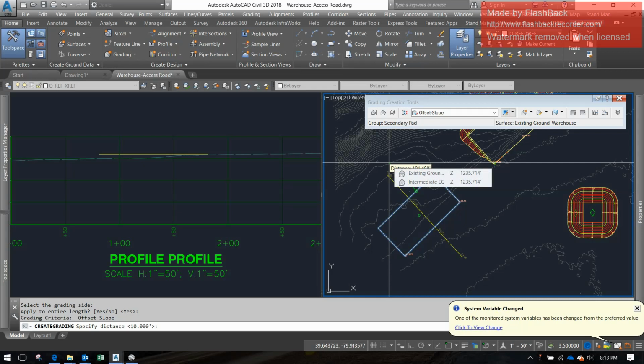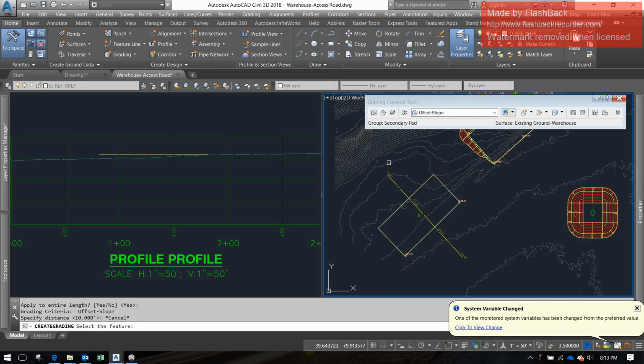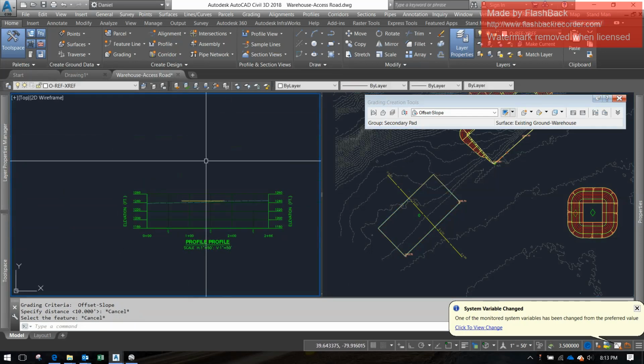I want it to have side slopes that are 10 feet long, and I want those side slopes to be a 2-to-1 slope. So essentially I want the berm to be 5 feet high, if you work the math out on that. And then I want to have a 5-foot top width, right? So what I want is something like this.